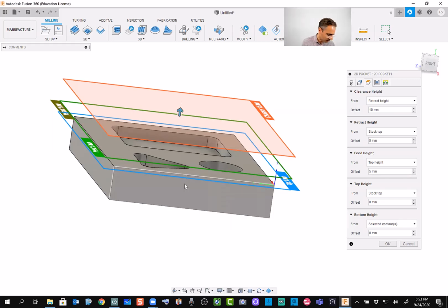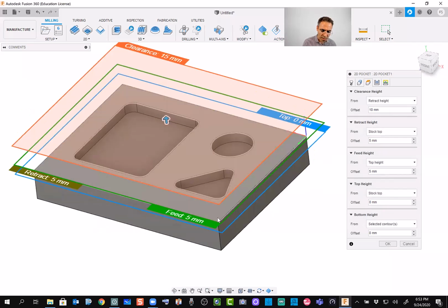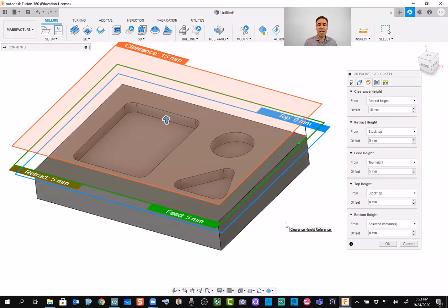The more important one is this 0 layer, this blue one, which sometimes people change that number. They want their first layer of machining just to be air, nothing else. Like they just want to see the tool path. The machine doesn't do anything for you, just cuts air, moving above the surface so they can check that everything is okay. We can move these things up and down, but the program does a nice job, selecting the numbers for us.